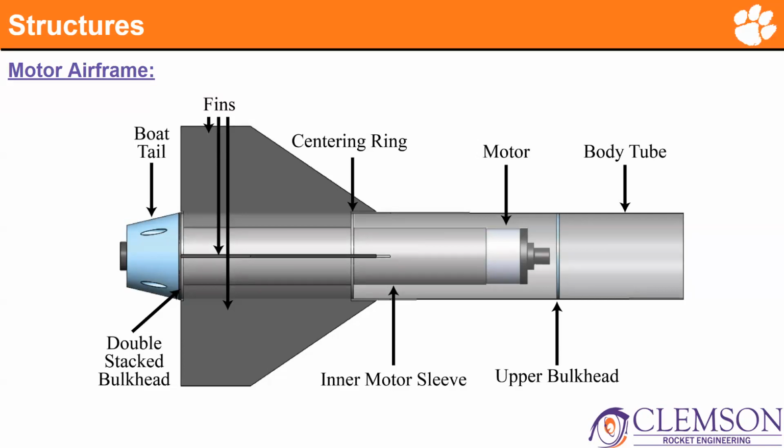I've switched back to the back one. Sorry, I changed subjects on you real quick. So when you're inserting that motor case into the motor tube and you got it almost all the way in, the rear closure, meaning near the nozzle end of it, should be stopping.